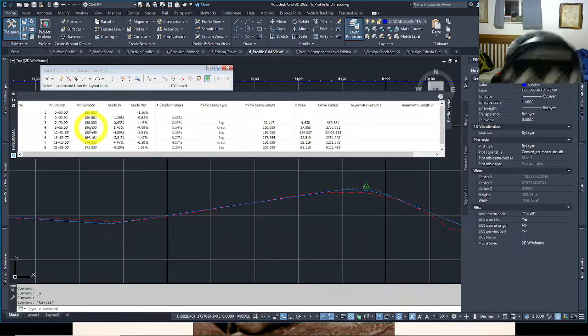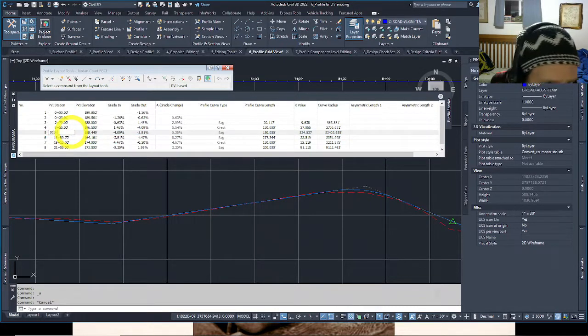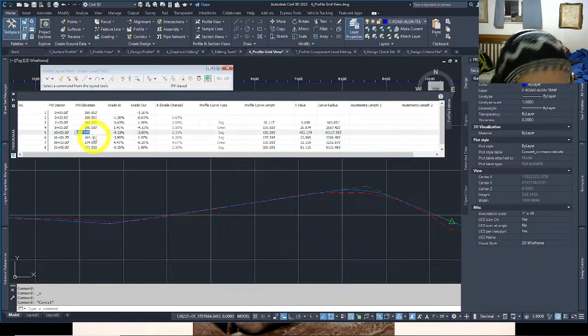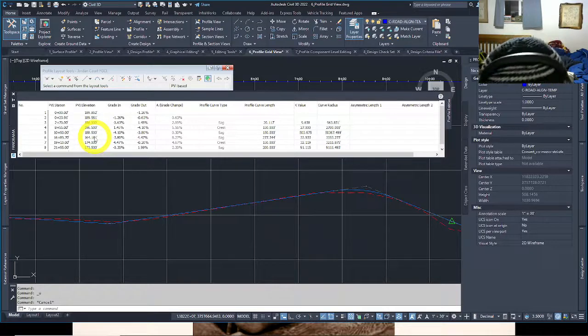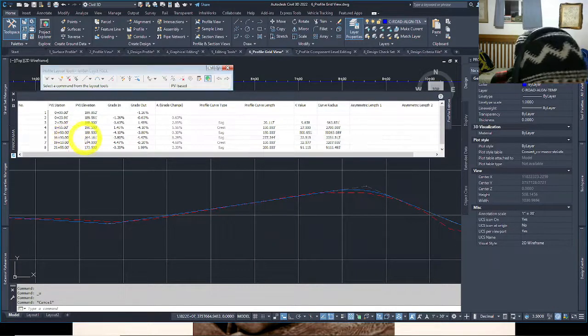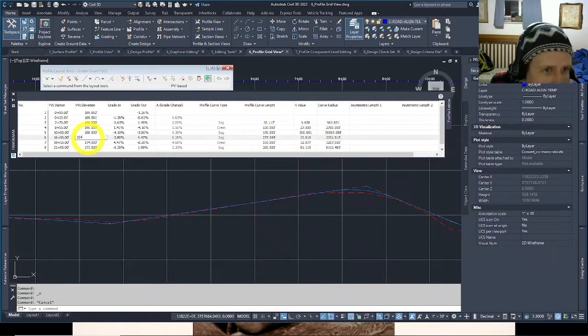that certain highway agencies, like federal highway agencies, a lot of times like PVIs and also in the horizontal alignments to be in even stationings a lot of times. That's some of their design standards. So it depends who you're working for. These things are important. Sometimes they're not. So if a small private developer, they could maybe care less about some of this stuff, but it's nice to have neat plans too, so you can get around and the contractor can understand them if there's a road or a canal or pipe network being built.